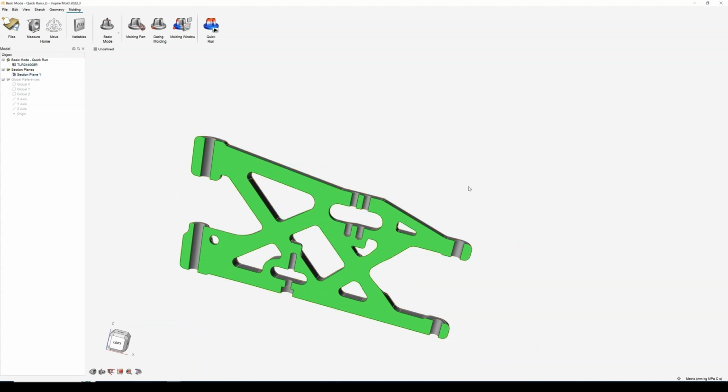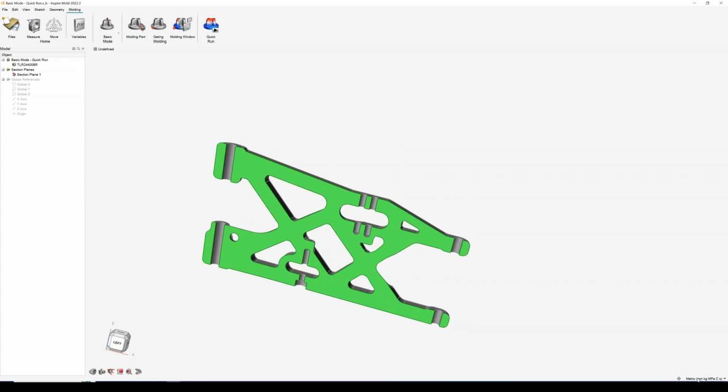In the bottom right-hand corner, you've got your unit system. So here you can go from metric to imperial. You can also customize units. So if you like to see your temperature in something different to Celsius, or your pressure's different, and all that sort of stuff, you can customize it all in this box in the bottom right.